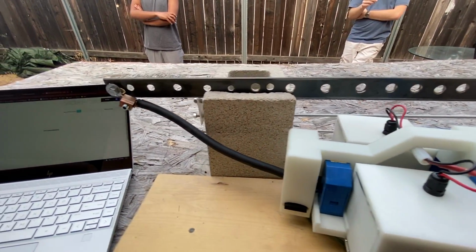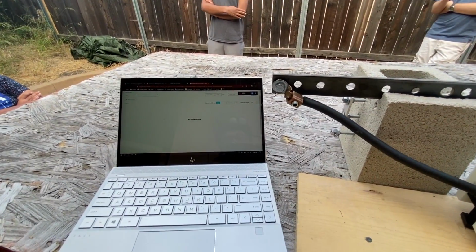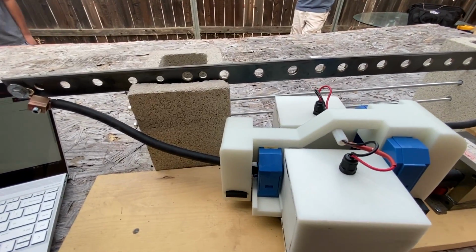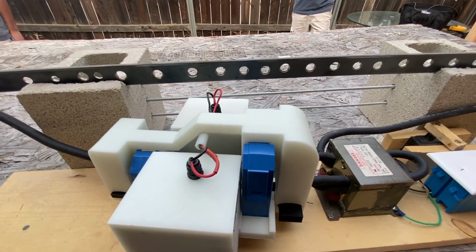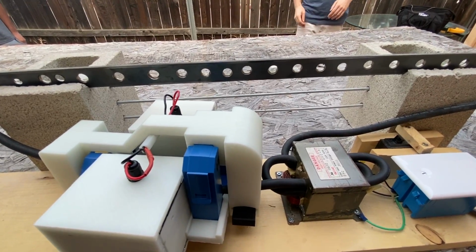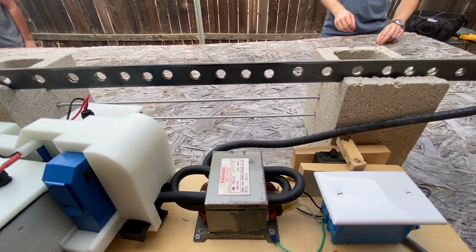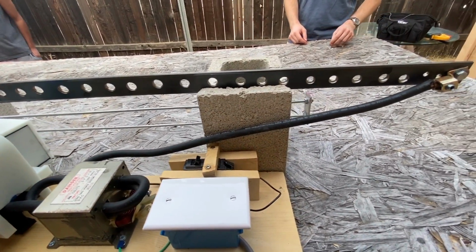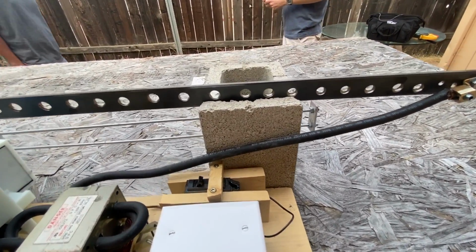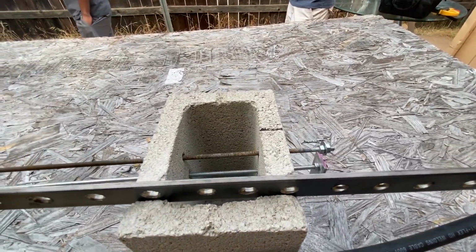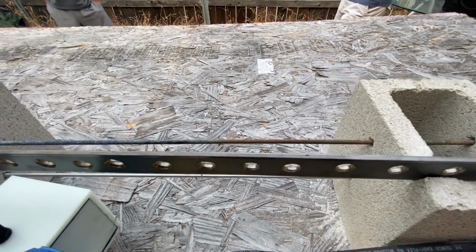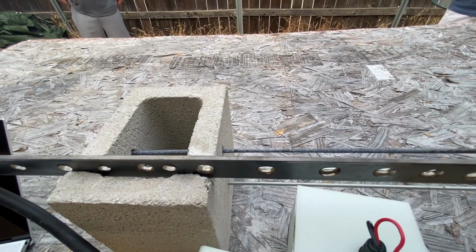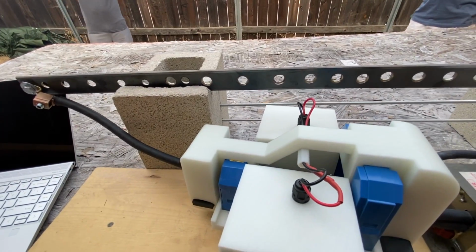This type of data collection also allows for extraneous events or rare occurrences such as downed power lines. The accelerometer would help provide information, as well as the LTE connection in detecting where this power line went down. These open circuit conditions and these extremes can help establish different types of trends that can be pertinent to the utility, and what they do with that data and how they perceive it is something that can just aid with fire mitigation and other stuff.